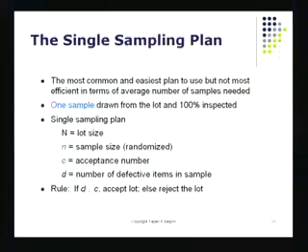So I must use a systematic plan. It's been worked out keeping in mind AQL, RQL, and the 2 risks, the consumer's risk and the producer's risk. Those 4 items have to be taken together: AQL, RQL, consumer's risk and producer's risk. Those 4 items together will determine this n and C. And let's see how we do that.